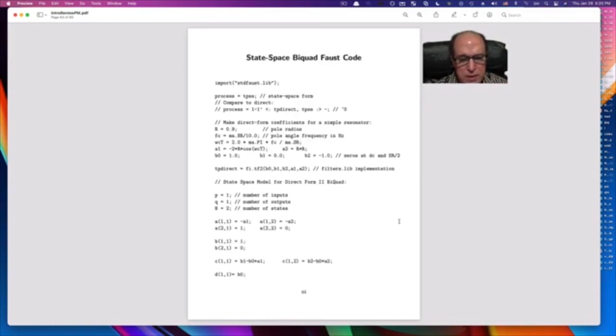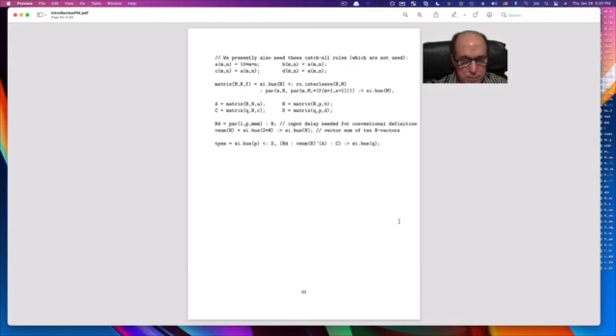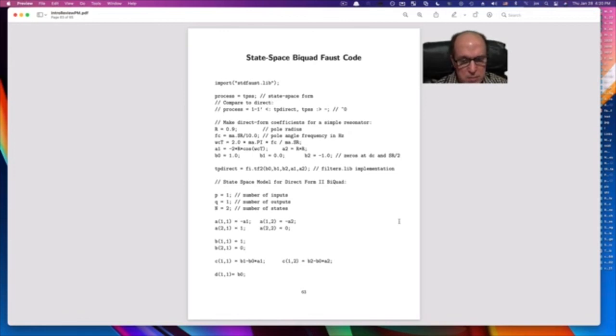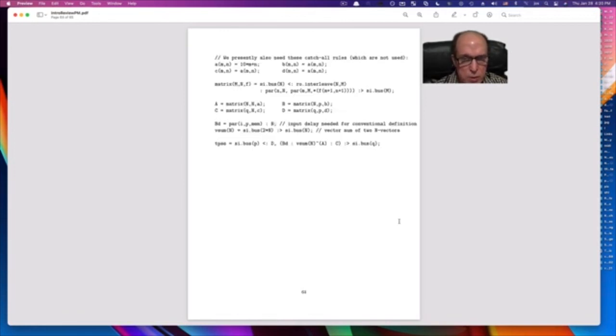But just intuitively, it's reasonable to know that your controllability and observability of a system have to do with whether or not there are zeros in the way. So if there's a zero canceling a mode in your system, then you can't control it, you can't observe it. And so you can see that it's different whether you're going in or coming out as to whether you have 0 coming in or 0 coming out. Just a little by the way on state space.